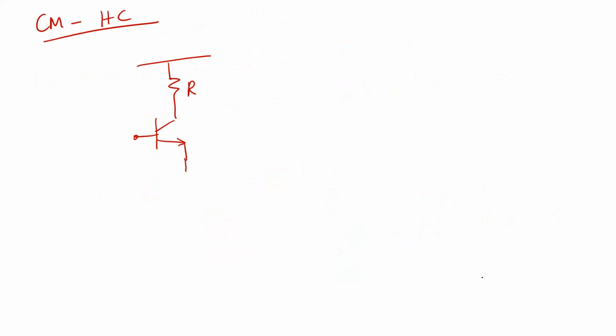So how can you split this resistor? You can split this resistor by saying there is some R tail here. The R tail can be an explicit R tail or it can be the R naught. But how do you put it? Because it is a half circuit, you put it as 2 times R tail, so that when you join both circuits together, you get back the original circuit. You take two half circuits, join them together, and you should get back your original circuit. So in that case, you need to use 2 times R tail. So this is your common mode half circuit.